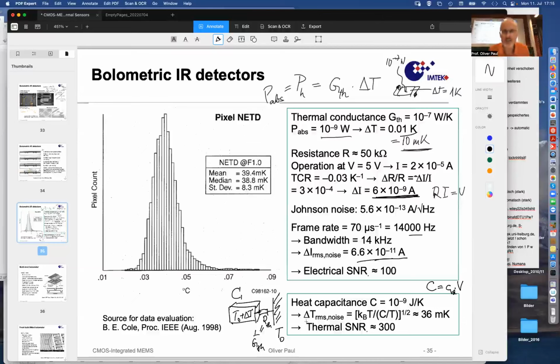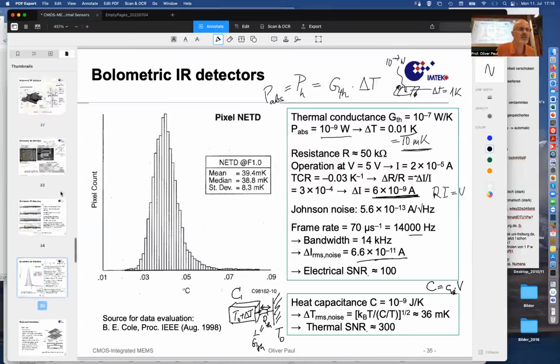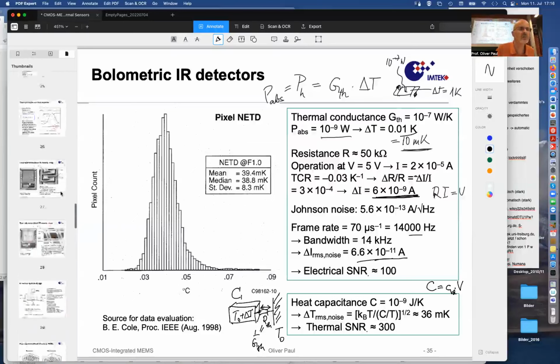So that is one thing. But then the interesting thing is that because of that back and forth conduction, this quantized thermal conduction, there will be this thermal root mean square noise in temperature. And that is given by this square root, which looks kind of similar to another expression which we have seen, KBT over C, the square root. You have seen that on which page? Let me see.